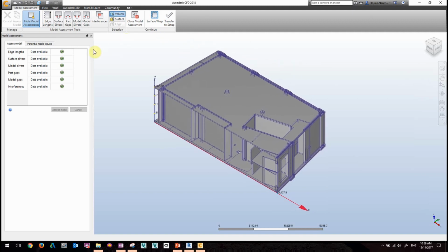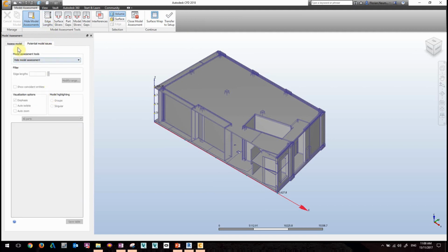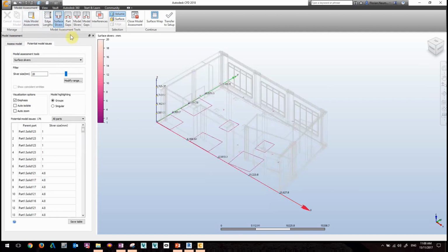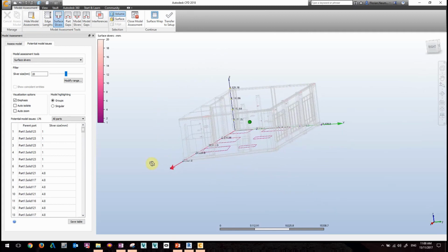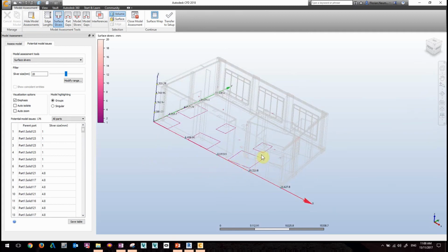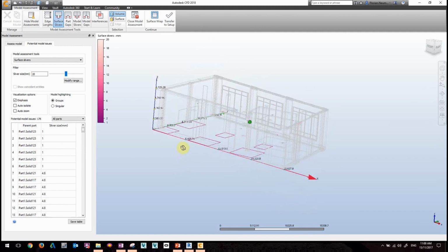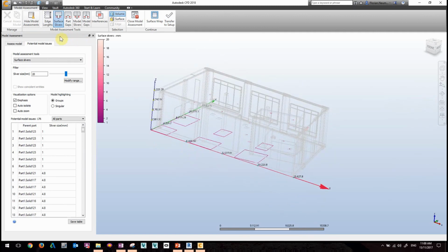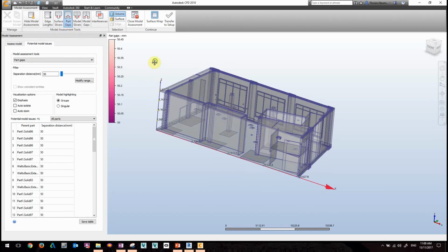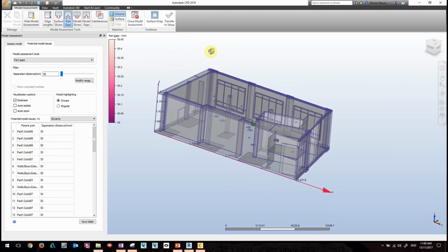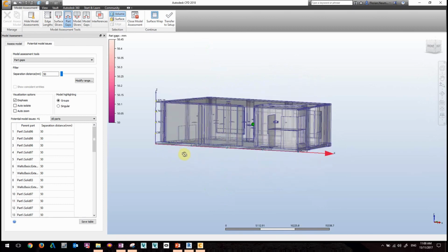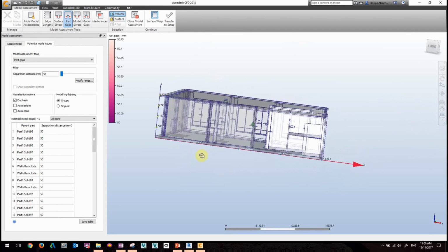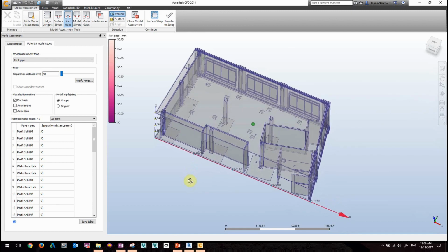What I want to do now is run through my potential model issues, in terms, for instance, of any sliver spaces. We see from the model that we don't have any big issues with the windows, but on the bottom there's probably some structural stuff which might pop through. When it comes to any parts or gaps, it seems somebody was cleaning up the model already, so we can focus on the workflow rather than on CFD training. There are some cool other classes around.